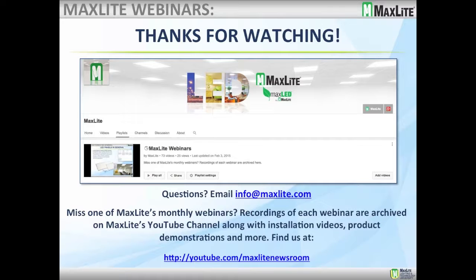One of the things we also have is on our data sheets, MaxLite puts some dimmers that they have tested for compatibility. So it's always a good place to start to take a look at the data sheet. If you have a particular dimmer and you don't see it on the data sheet, then reach out to our technical support team here at MaxLite, and we'll be able to tell you yes or no if we feel that dimmer will work.